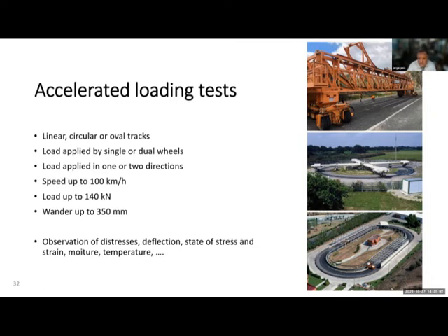And these accelerated load facilities can apply loads up to 140 kilonewtons and speeds up to 100 kilometers per hour and wander up to 350 millimeters.